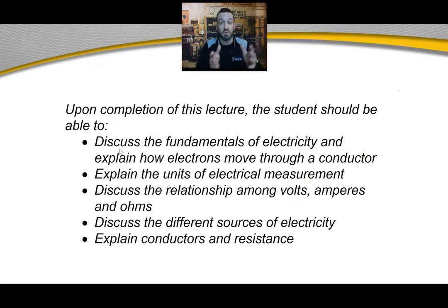Okay. If you have a corroded connector or a bad ground, that is high resistance, right? That is like stomping on a garden hose. You're going to lose flow. The pressure may still be the same, but you lose flow, you lose wattage, so your bulb is dim, okay? So that relationship is going to be absolutely key. Just breaking it down that simple. Why don't I have ground? Well, high resistance, right?